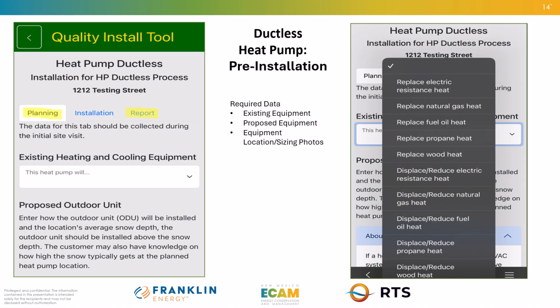Enter how the outdoor unit, ODU, will be installed and the location's average snow depth. The outdoor unit should be installed above the snow depth. The customer may also have knowledge on how high the snow typically gets at the planned heat pump location.